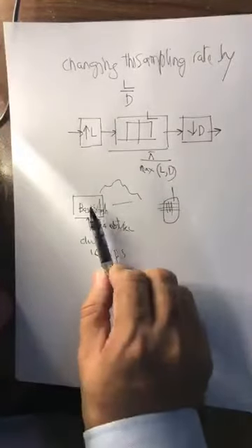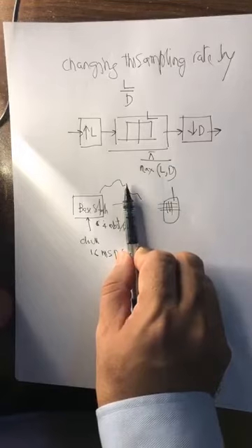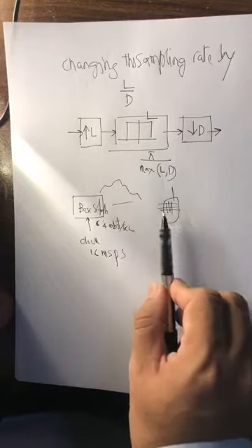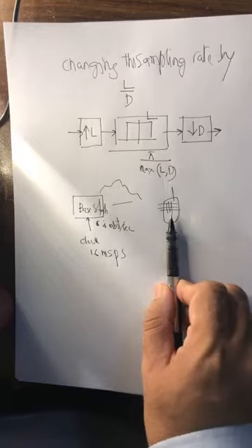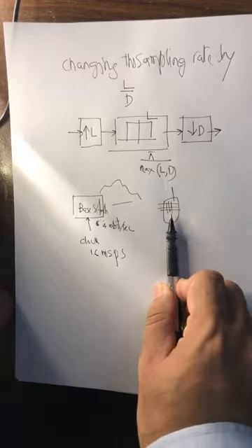A sampled signal is converted into an analog signal, transmitted in the air, and comes to your mobile phone. Your mobile phone has a slightly different clock, which is 0.0001 different. So in a few seconds it generates another sample. It has absolutely no clue what to do with this sample.